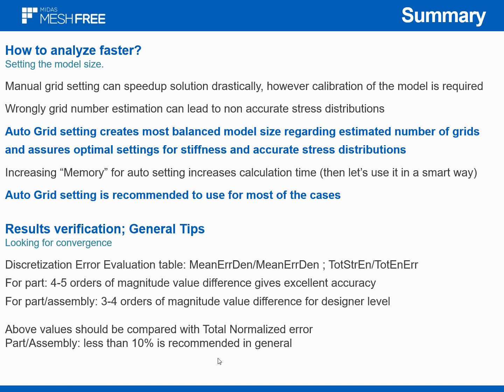So my recommendation is to use the amount of memory from 4 to 8 or 16 gigabytes if you can, but not lower. My advice is to focus on the part which requires improvement in terms of the number of the blocks, and then use auto setting for the rest of the parts. But it depends. So that's the general conclusion, that automatic is still the best, and now I think you understand why.